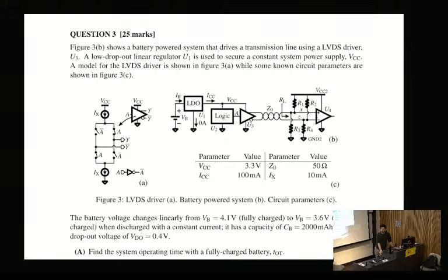Yes, exactly. So we transmit them differentially so that, again, if one signal picks up noise, the other is likely also picking up the same amount of noise. It's a difference amplifier, so we'll remove that noise that it picks up. It's never a good idea to transmit signals with one referenced to the ground and the other with just a signal, because then they pick up unequal amounts of noise.